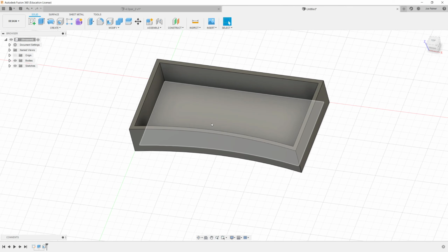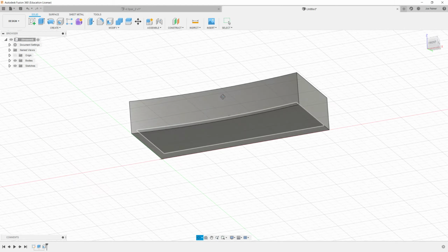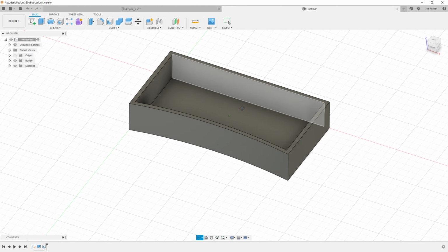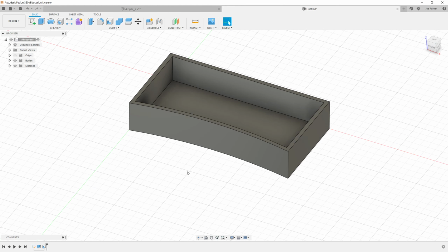And then what I'm going to do next is add in the material for that center web. Now, when I created my first extrude feature, Fusion 360 has automatically hidden that sketch because it believes I'm done with it. I need to use some more information from that sketch, so I'm going to go to the browser in the top left corner of my window. I'm going to click the arrow next to sketches, and press the eye icon to turn on the sketch which was previously hidden.